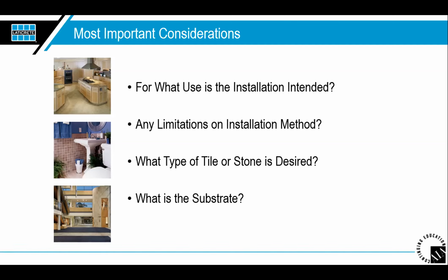So again, if you're setting glass or if you're setting natural stone, you could be limited in what type of installation materials you need, due to the effects that the stone might have from the Portland cements or from different colors of grout, for example. I'm sure we've all been a part of projects where we've seen staining occur or wet spots occur that we couldn't get to disappear. So again, that comes down to using the correct installation products for that job.